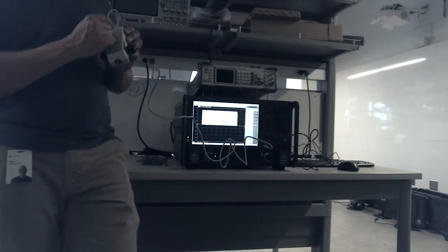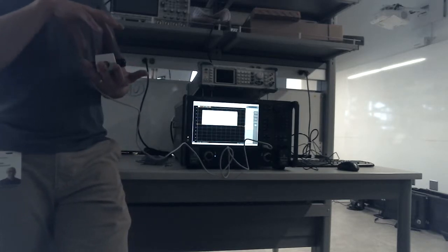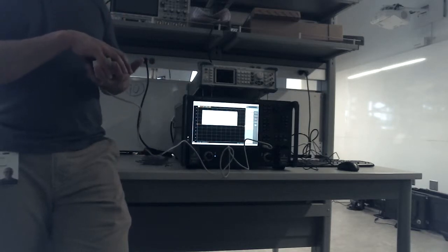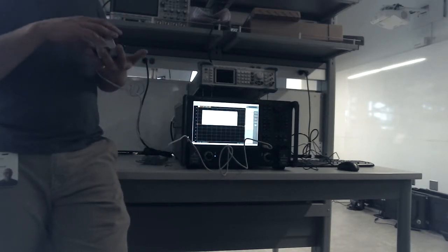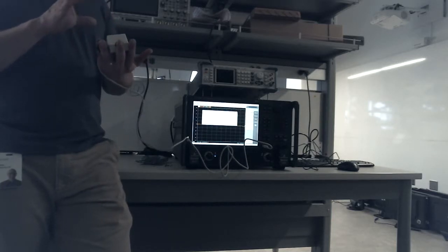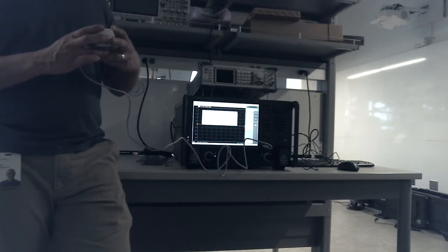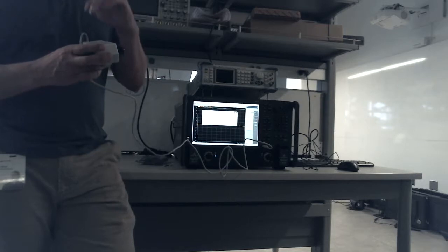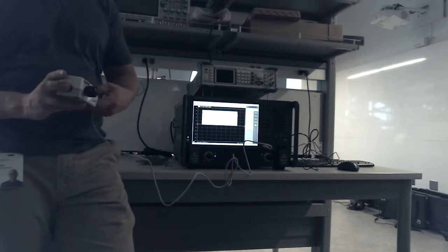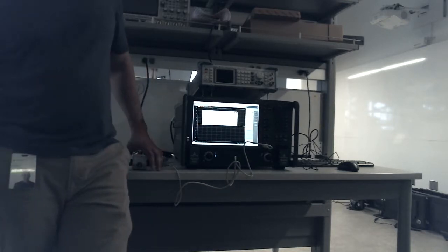So you'll see there's a wait and ready light on here. It has a number of electronically tunable loads inside the calibration module. These need to come up to a certain temperature, because when we've characterized the response of these loads, we want to make sure that when we're doing the calibration, the temperature within the standard is the same as when it was initially characterized in our calibration facilities. So it has built-in circuits inside so that we can test with this module?